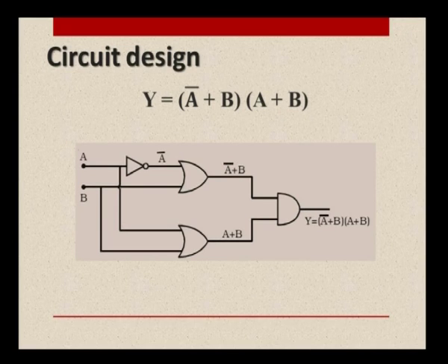And when we look at the stepwise outputs, let us have the diagram once again. See, the input has A bar. So, here the input A is complemented using a NOT gate and we get this, and B is directly given. So, A bar and B inputs are given to the OR gate here, and we get an OR operated output. Same way, A and B are directly given here for the second OR gate. So, it is operated by the OR gate here, and finally the AND gate combines them with the AND operation. So, it has 4 gates if we do not have a complement part as input directly.